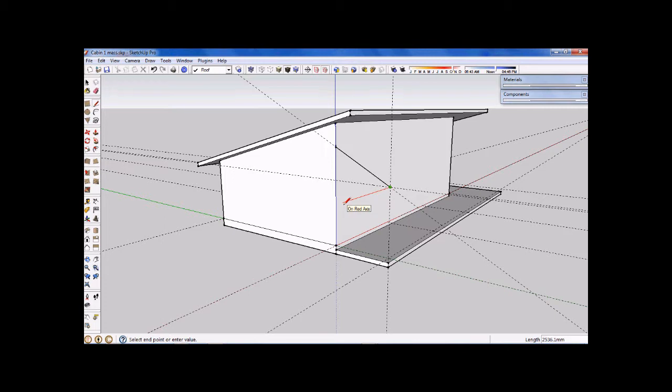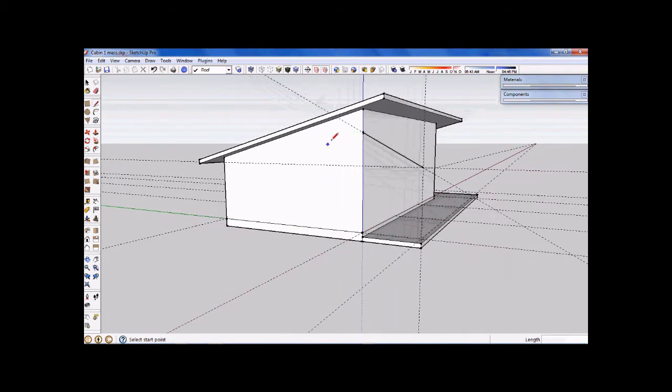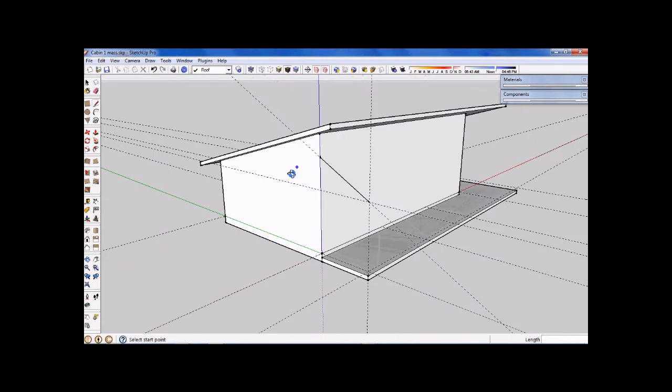Now we've got a couple of other options that we can use. We can either create an offset line from this construction line as to the thickness of the roof, or we can start to draw a piece of our roof back in the plane axes directions. It's a little bit tricky to offset this line in a straight perpendicular plane that would stay in this gabled end plane. So from a beginner's point of view, we might initially keep drawing on roof axis,